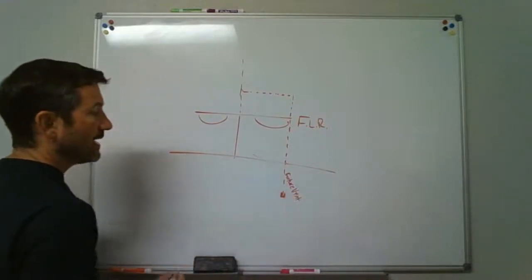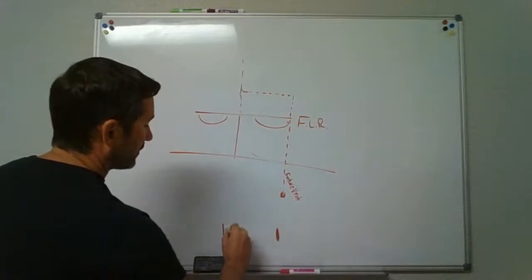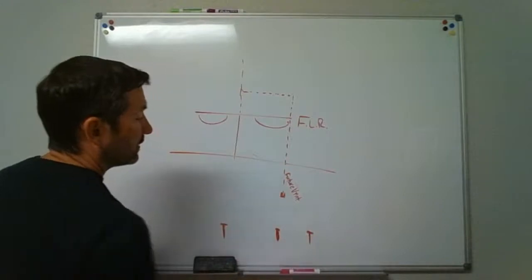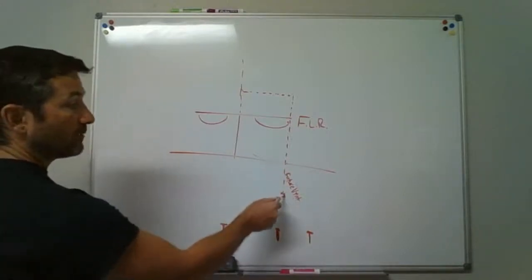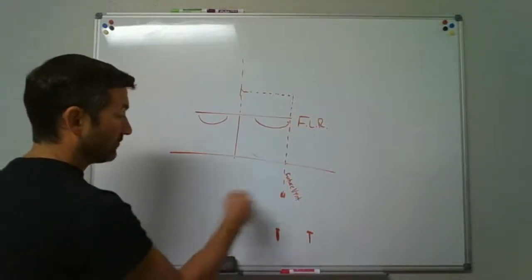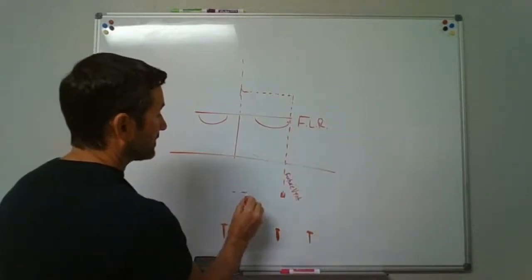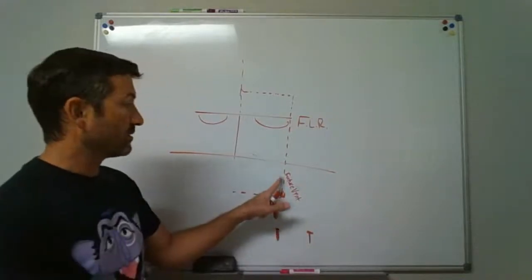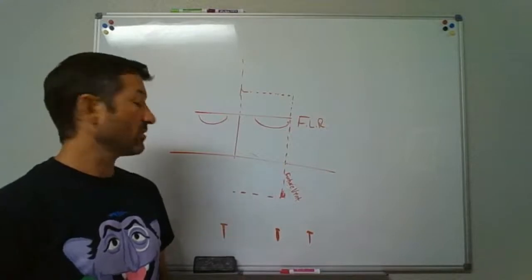Okay. Now, downstairs they've got all these plumbing pipes coming up, stubbed up through the floor. They've got them here and here and here, and I'll cap them all off. Future drains. But since I have future drains, I need to run one down, cap it off, and label it future vent, so that when I rough these in at some time later in the future, I've got a place I can run over and tie those vents up. I need to make sure that that's going to be half the size of the drain that it's serving.